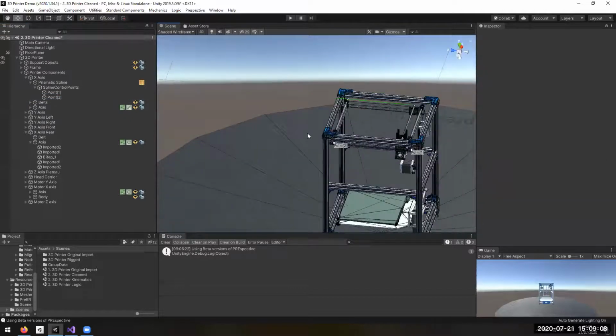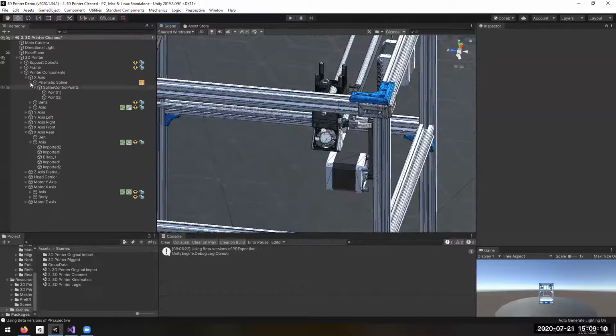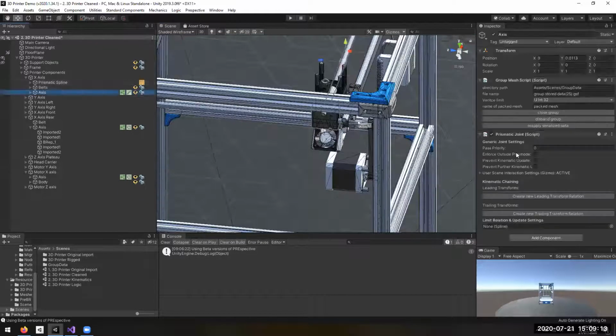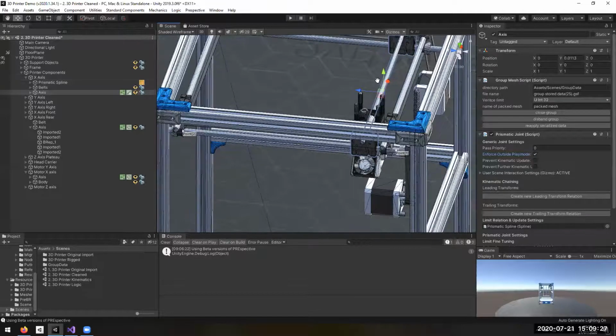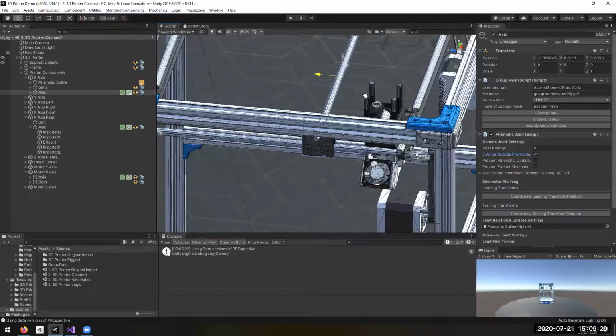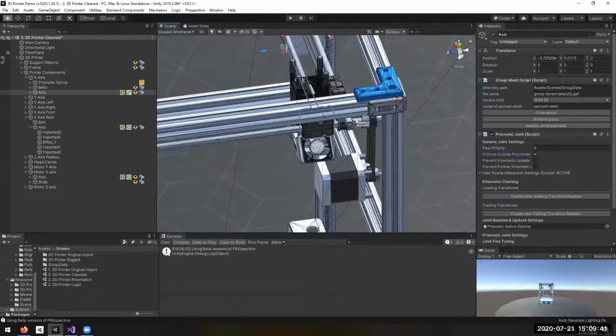Okay. And then I'm going to set this spline as the constraining spline for the prismatic joint, which you can do at the bottom here. So just drag this spline in. And I'm going to enforce it. And the same kinematics controller which handles the wheel joint will now handle this object over this prismatic joint. I can still move it over this direction, but it's no longer able to move in any other direction, as you can see here. Okay, so let me set this back so that it aligns like this.